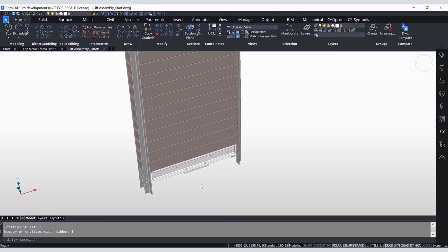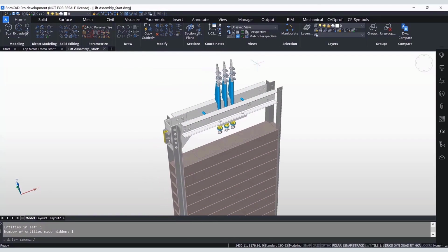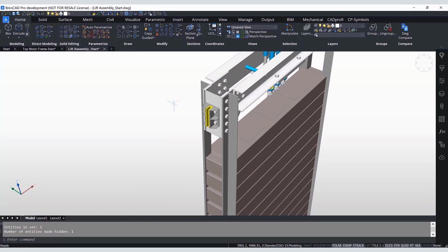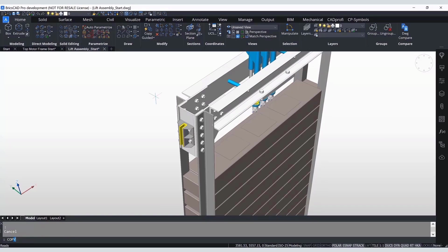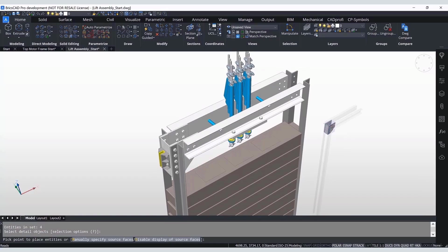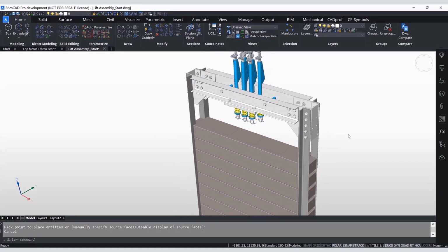This is a good opportunity to show that the copy-guided 3D tool is also able to copy several solids and blocks at once. And you know the parts will be placed correctly. Like before, with more parts selected, you will get a similar preview and the same functionality as you saw before. So we select several plates and place them to the opposite corner of the model. Let's check that everything is correct.